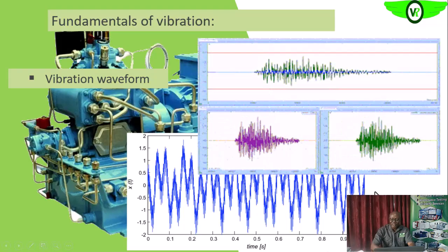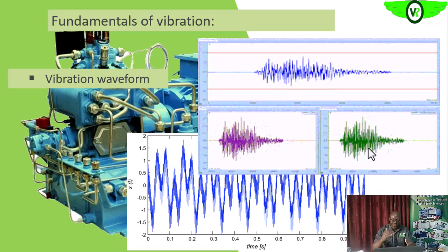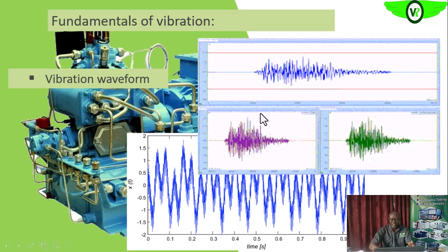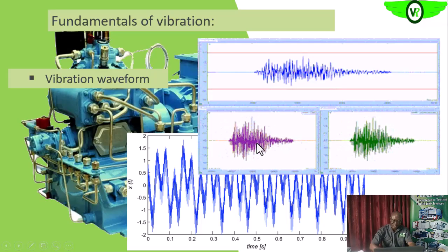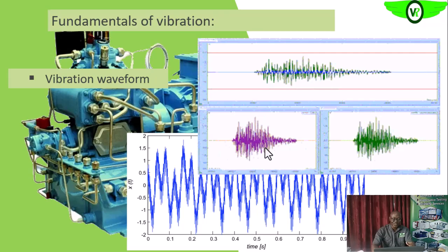So this is what you will definitely see in real life. So it will make little or no sense. Okay, apart from the vibration amplitude, the overall vibration that you can actually glean from this will tell you that the vibration is increasing, by merely looking at the amplitude here. So if it is increasing, you will know that something is amiss. Something is contributing more than what is normal. So we'll see how that can make sense to us later.